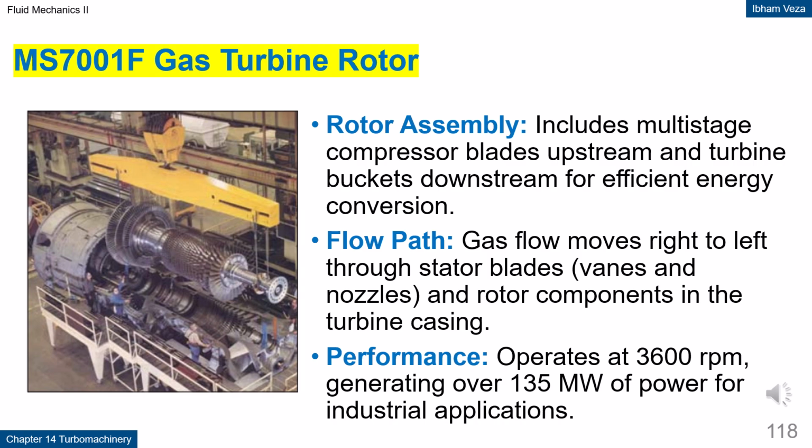MS 7001F gas turbine rotor. This rotor shows the integration of multi-stage compressors and turbines on a single shaft. The gas flow passes through stators and rotors sequentially to undergo compression, combustion, and expansion.